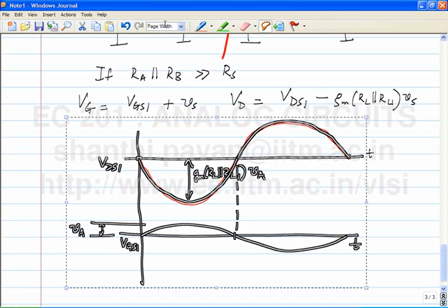So if I increase VA, the drain is coming down, which basically means that the drain and gate are coming close together in potential. In other words, the drain is trying to go below the gate. And it seems clear that it's only a matter of increasing VA. Eventually the drain will definitely go 1 VT below the gate. To drive home the point,